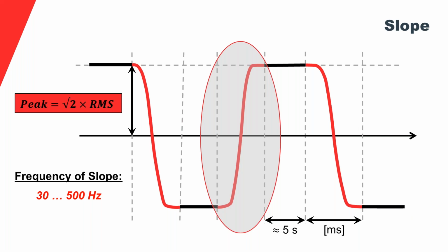And the second thing, which I mentioned the last time in the webinar as well: the cosine rectangular was never intended to be used for diagnostics testing. The customers came to us and said, hey, can we use that? And we said, we don't know. So there were 4 major studies conducted. And what pretty much was done was that the test results were compared to damped AC. And since damped AC was already proven to be comparable to power frequency, then the logical conclusion is cosine rectangular is comparable to power frequency.